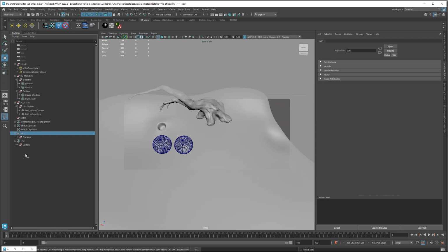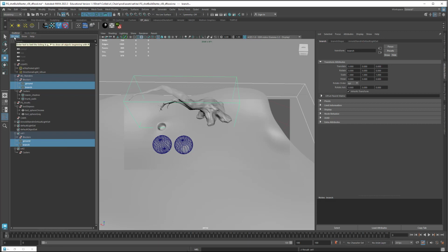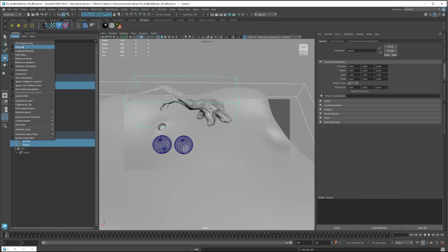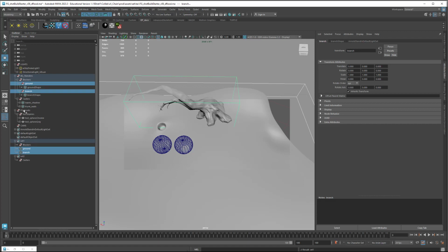And it didn't work. What we need to do actually is, for one thing, it didn't load in these things at all. And another thing is that even if I took these here, these stand-ins, and read them into this group, this would actually not work because this is the transform, and what I need in here is the shape node. So I need to come into here, turn on shapes, and there we go.